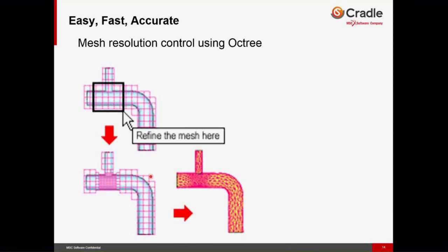Just to remind you, we are not simulating the behavior that is happening in the solid or among the solid surfaces. Like FEM, you care about the solids. But we do care about something that is happening outside of the solids, which is the fluid region. Controlling the mesh only along the solid surface is not good enough for CFD.